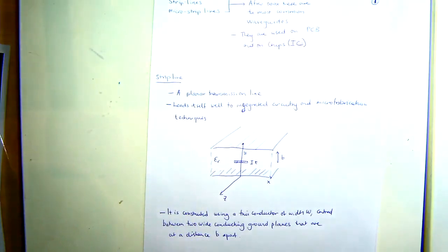And essentially, the reason why I'm teaching you about microstrips and strip lines is when you're designing waveguides, or ways in order to transfer energy across a PCB board or a chip, there's usually three techniques that you use. You either use a microstrip line, a strip line, or a coplanar waveguide. But I'm not going to talk about a coplanar waveguide today. We're only going to talk about those two. That's the reason why I'm telling you. If you're designing waveguides with a known impedance, they're the two techniques that you usually use, right?